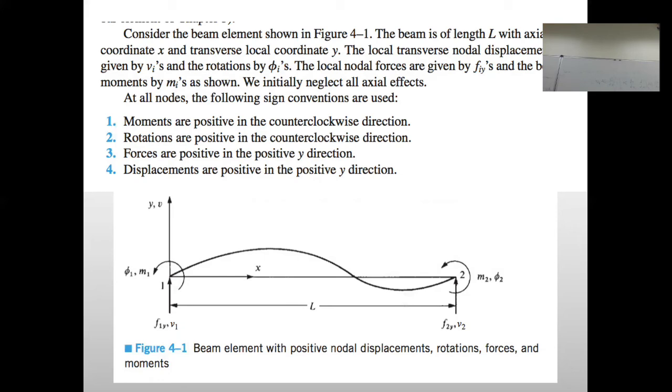Okay. How we are going to derive the stiffness? Using direct method. Do you remember the truss? How did we find EA over L, 1 minus 1 minus 1? I think we have two figures, if you remember. One figure for finite element and one figure for sign convention. For the sign convention, we have T here and T here.